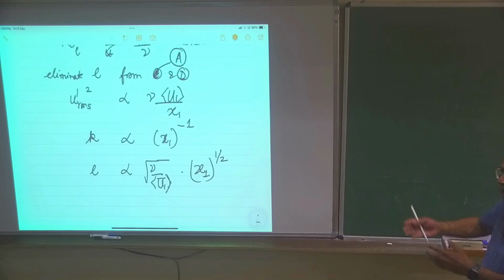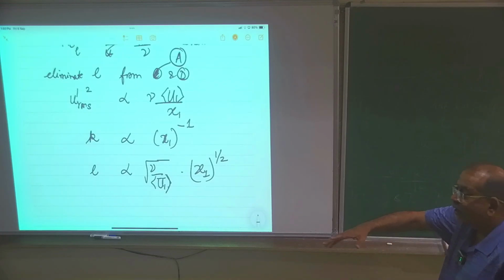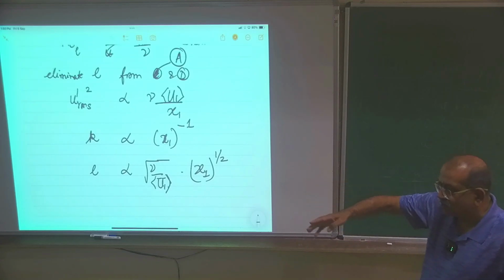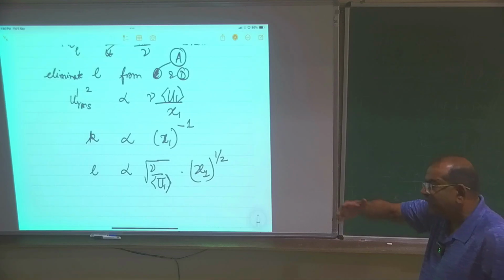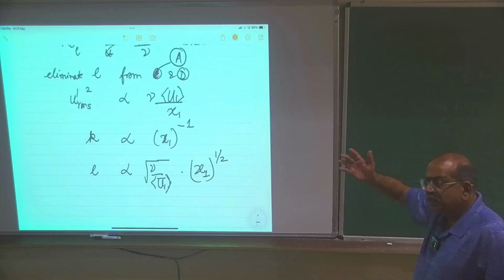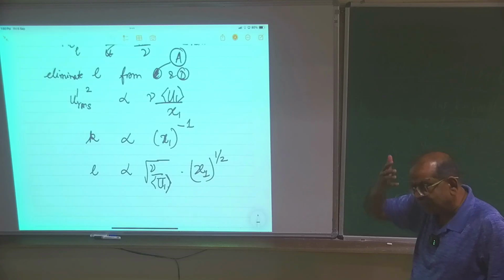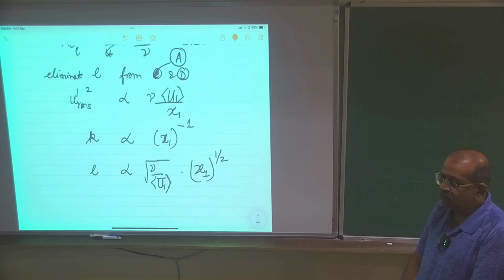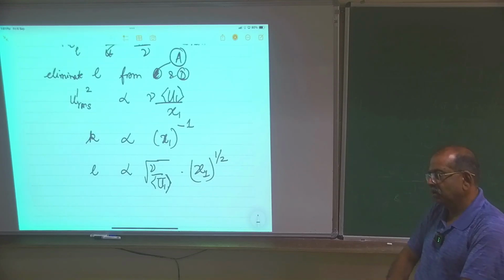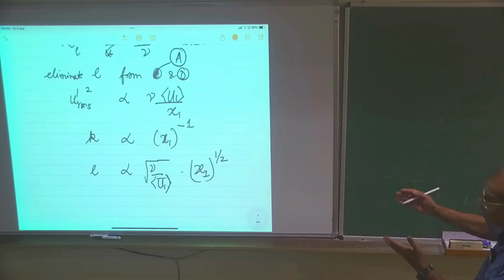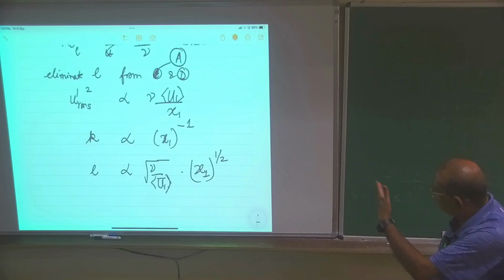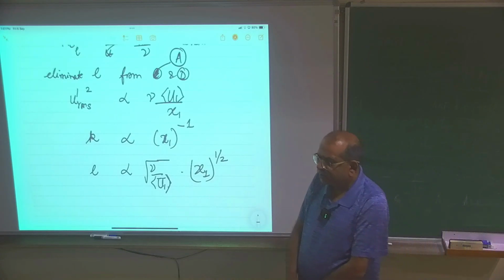Why is the length scale increasing? But see, what is going to happen is this: as the flow goes down, the length scale increases, but then in the decaying portion, in the dissipative portion, this doesn't work. Then everything will fall down. But later it will become smaller. But in the few regions downstream, it is increasing, and it's also experimentally verified.